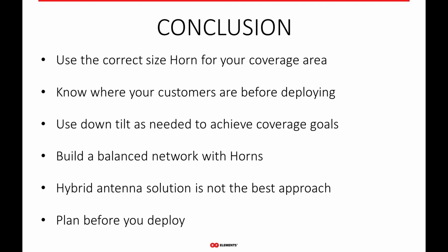And you give your contractor this go, no go gauge, right? The customer has to be between negative 50 and negative 60. If it's anything over negative 60, you shouldn't connect them, right? So they go out to a tower and they may be using a higher gain CPE, and the customer happens to be a mile away from your tower.